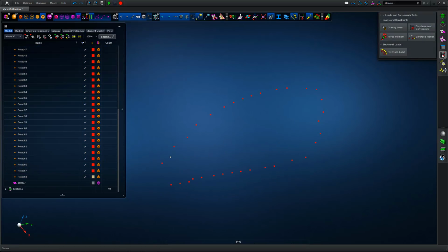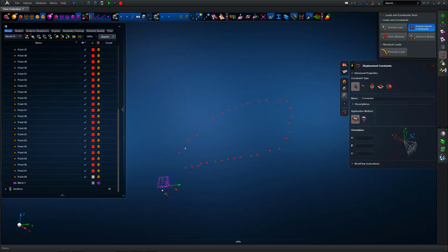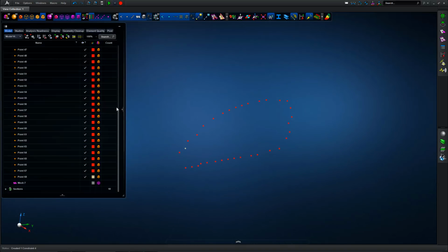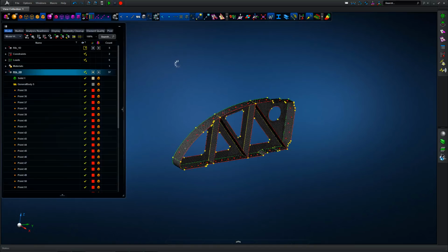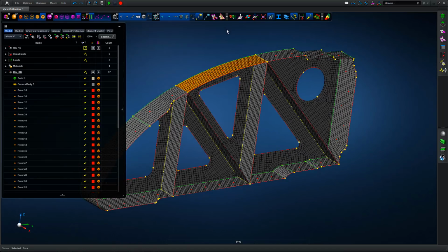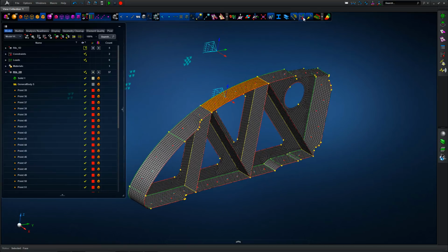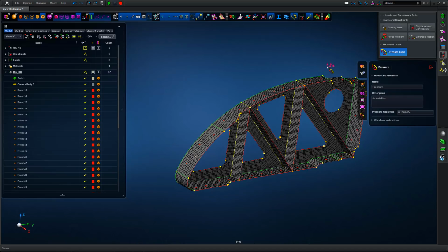So moving on to model verification, or rather running some loads through the model just to understand how the model is going to work. This level model would probably be tied into a sub-assembly through the use of some idealized fasteners, maybe a discrete node-to-node fastener or some kind of shared load transfer fastener, but in this case the fasteners are all defined at these hard points. So we're going to simply define a boundary condition on those hard points, and then run some pressure loading through the rib webs to give us an out of plane bending action, and then understand what that does in terms of the load transfer through the fasteners.